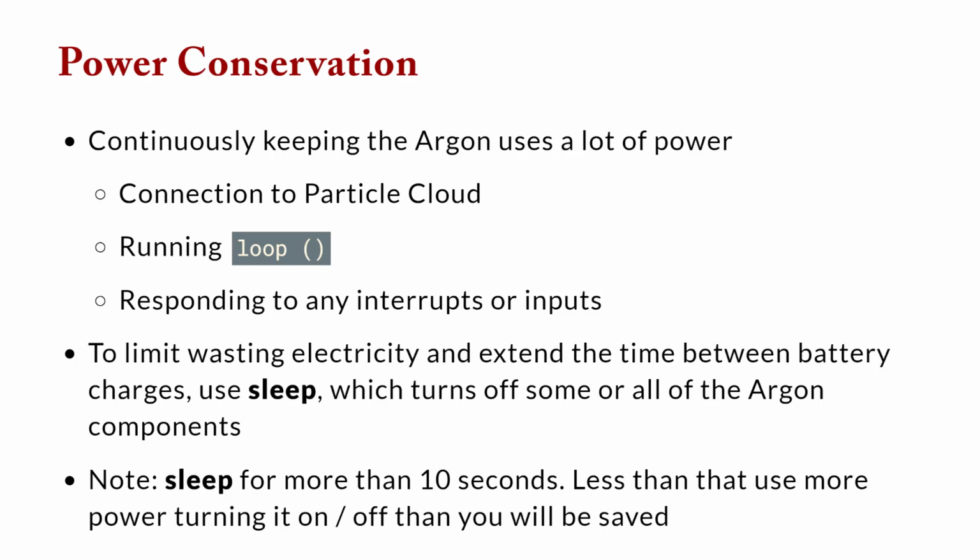One point to note here, this is just recommended by the guidelines from Particle, which is that if you're going to sleep your device, do it for more than 10 seconds. If you're going to do it for less than 10 seconds, you're actually better off leaving it on, because there's a certain amount of energy and battery drain that happens in turning on, turning off. And so if you turn it on and off every 5 seconds, you're going to be wasting power.